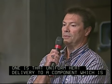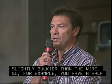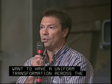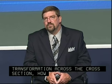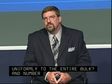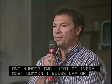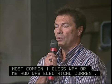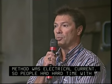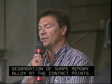If you have a 1/2 inch or 1 inch rod and you want a uniform transformation across the cross-section, how do you deliver heat uniformly to the entire bulk? And number 2, heat delivery, the most common method was electrical current, so people had a hard time with degradation of the shape memory alloy at the contact points. Have there been any advances since then?